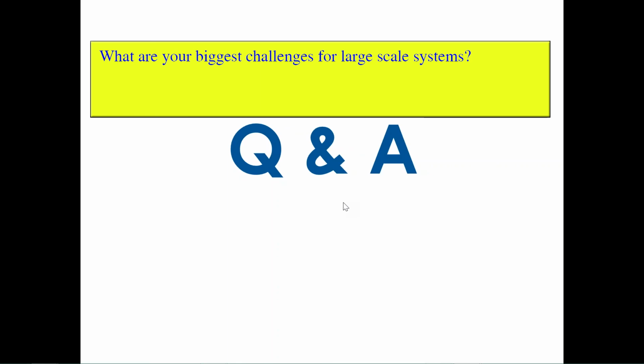For any large RO system, of course, you need to find pumps large enough, valves and instruments large enough, but for the most part, you're still using 8-inch membrane pressure vessels. You just use a lot more of them. So it's the same in a Desalitech process. RO scales very well.